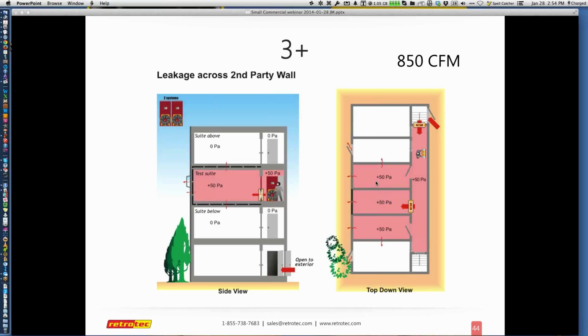So in theory, there would be one on the right, left, potentially above and below, all trying to subtract the CFM so I could isolate where I found my greatest leaks or issues were based upon multiple tests. And if I don't have access to these things, the best I could do is at least try to make sure I could create an opening for a pathway for the pressure to release itself, and make sure they were not having their HVAC system on or creating pressures that challenged my setup.